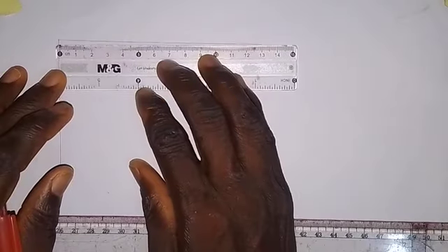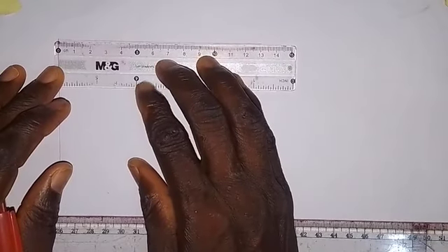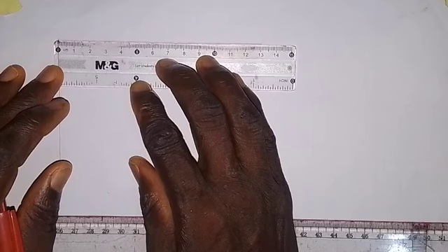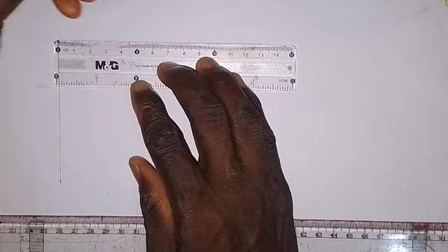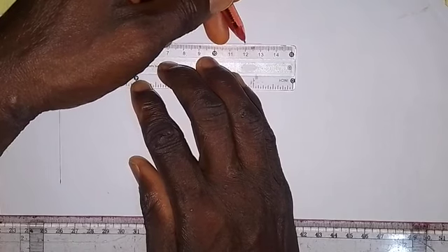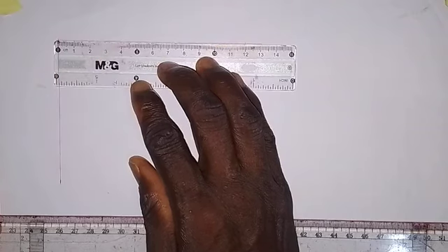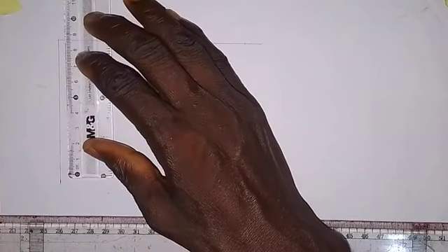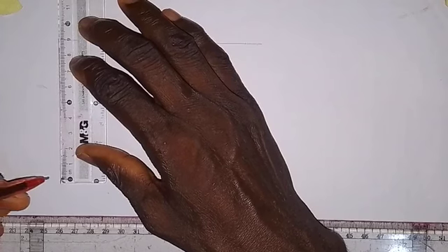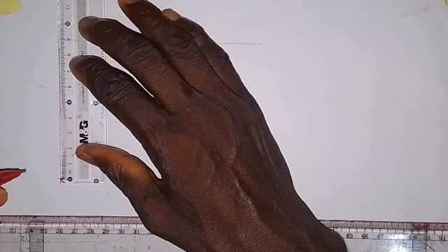So we are going to take measurement. The first measurement that we are going to take here, we take 120 millimeters. If we divide 12,000 by 100, as we are using a scale of 1:100, that will give us 120, which is equivalent to 12 centimeters. This is 120 millimeters, and the width of the bigger rectangle is 9,000 millimeters. So if we divide it by 100, that will give us 90 millimeters. So here we have 90 millimeters.